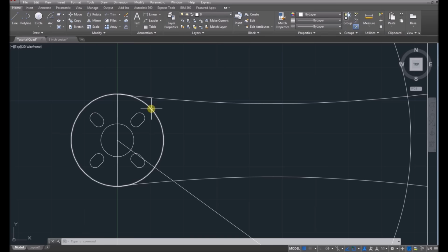Now, something we've forgotten is we need to get rid of this line in here, in exactly the same way as we did it for these little guys here. And I'll delete that there. So this is a trick. You can't have that kind of thing. That'll mess up the CNC machine.